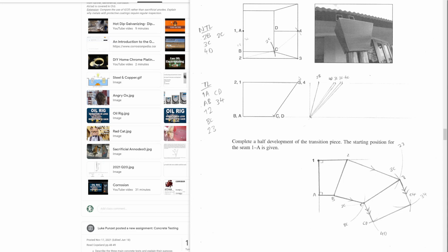We have a word for that. But for this plan distance, I've taken that distance with a compass, and I've just measured from here. I draw a line from here to here for that height distance. And then I get the hypotenuse. And the hypotenuse is the true length. So that's what I did.